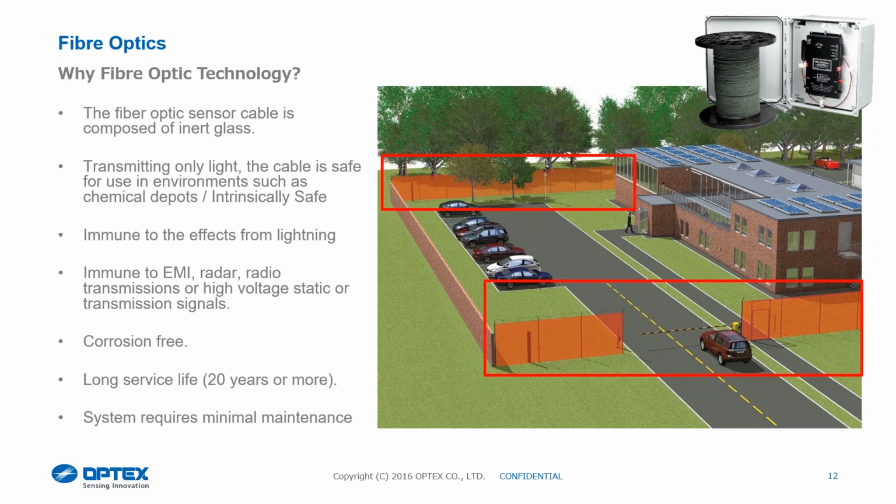A lot of copper-based systems, if you actually look at the small print on them, they'll all quote that you've got to change the copper cable after every 4 to 5 years. Again, that doesn't apply for the fibre system. There's no copper element, there's no corrosion element there. So we can give you a very, very long service life, typically around about 20 years when you've got the cables installed in a conduit out on a fence line.